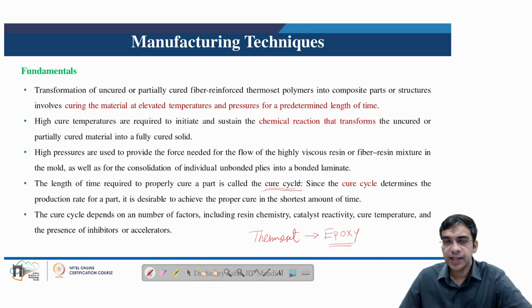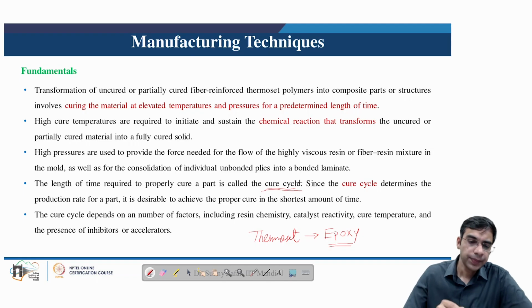The cure cycle also depends on other factors such as resin chemistry, catalyst reactivity, cure temperature, and presence of inhibitors or accelerators. So we will see these things in a little more detail in a moment.